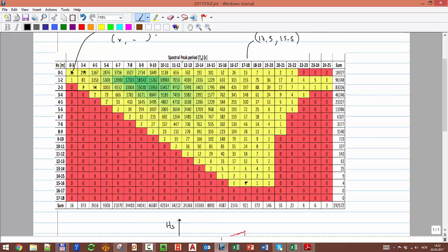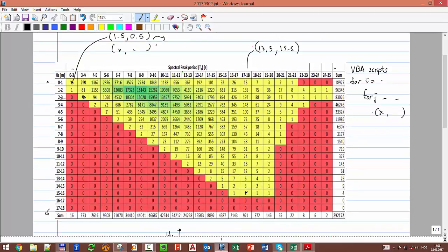If you want to use your VBA powers, you can use a VBA script, like a superpower, okay? And then you make a For i equal from here to here. Then you put another For j equal from here to here. And then you say take each element and make a pair, okay? Make a pair of points. You can also do that. We haven't discussed it here. I will see if we have time. But if not, you can do it manually. Okay? But I encourage you, for all of these repetitive tasks where you can detect a pattern, I suggest to explore doing it with VBA scripts.